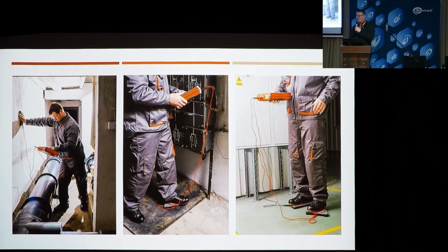So, I can see him right there. Found him. Anyway, he's a specialist in insulation measurements. So at the workshop, you can put a bit of pressure on him too and get him to talk about it. So here we have a method for measuring the insulation resistance of a wall. The second photo is the one in the middle, some kind of workstation there. So we connect one lead to the probe, the second to the protective conductor.